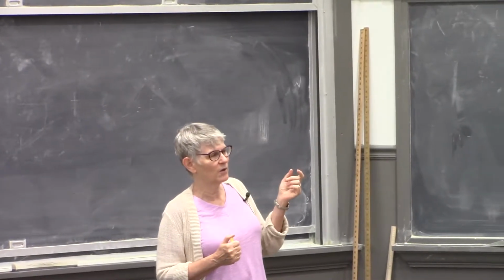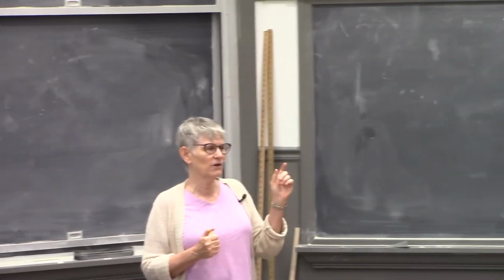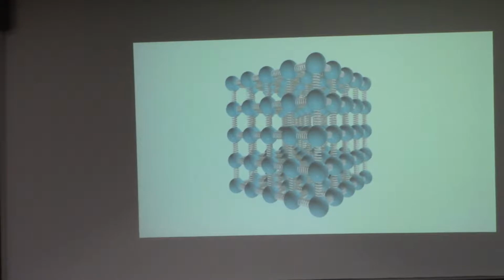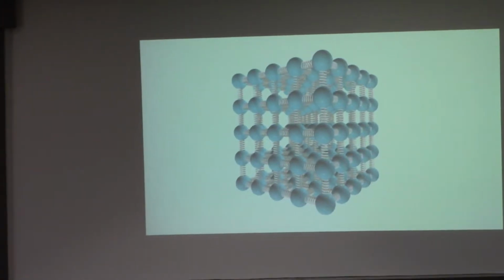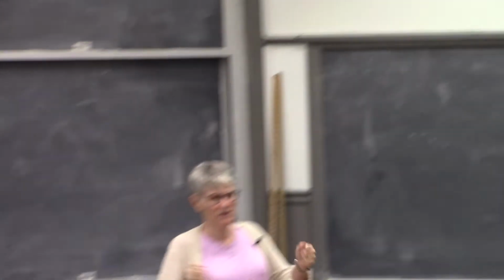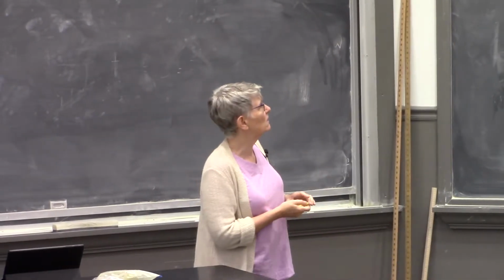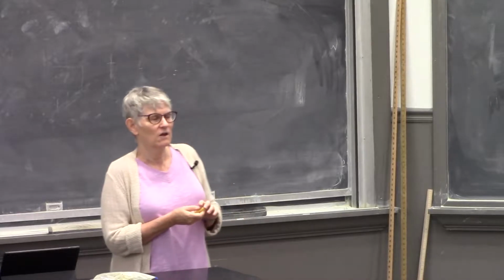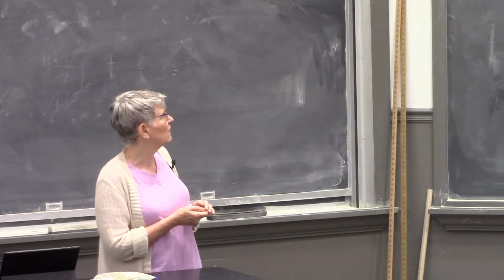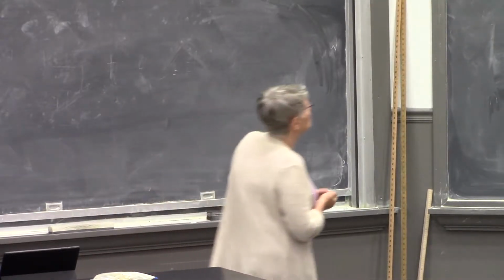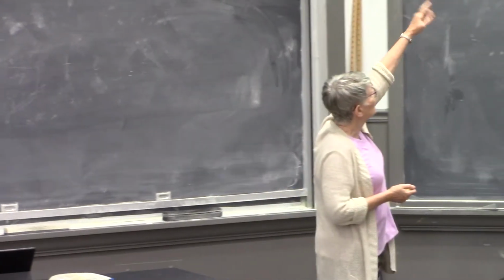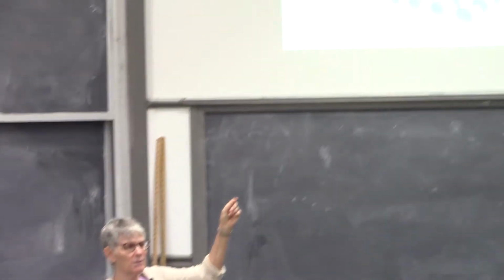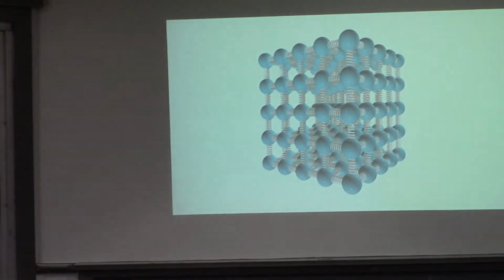And these covalent bonds, it turns out, are very spring-like in the sense that if you exert a force, you stretch it a certain amount, and if you exert twice the force, you stretch it twice as much. And so the enterprise that we were engaged in and didn't quite finish last Thursday was to determine the spring stiffness of one of these interatomic bonds modeled as a spring.